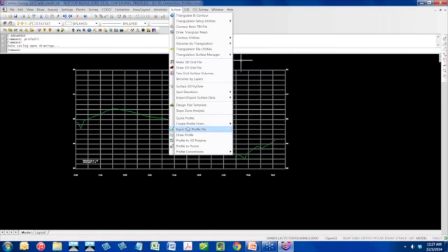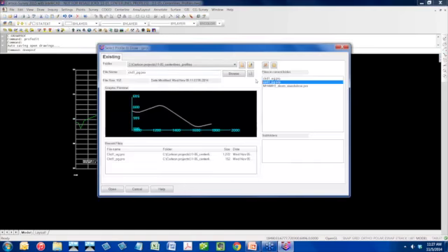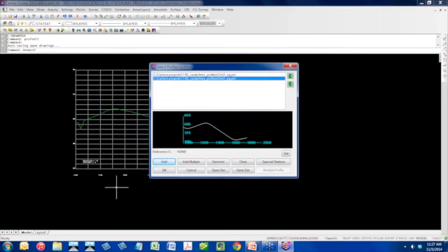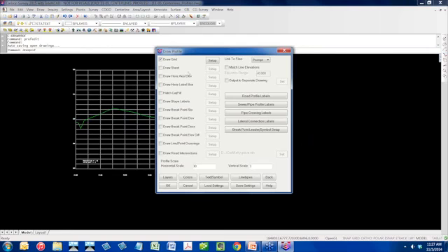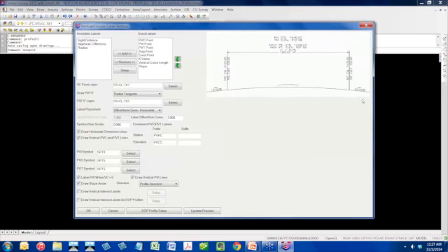If I go into Surface, Draw Profile, I'm going to add in the road profile now. So I've got two. Pick OK. I'm going to pretty much leave everything alone. If I look at the road profile labels, you can see what the labels are going to look like.